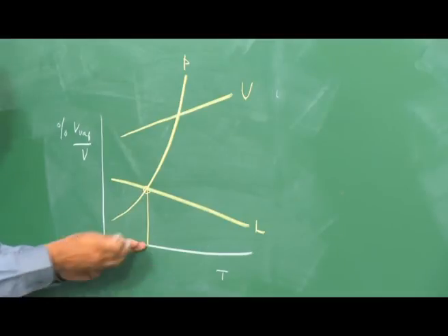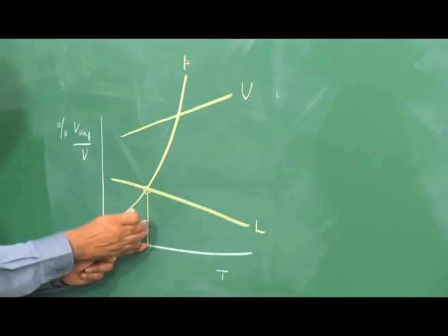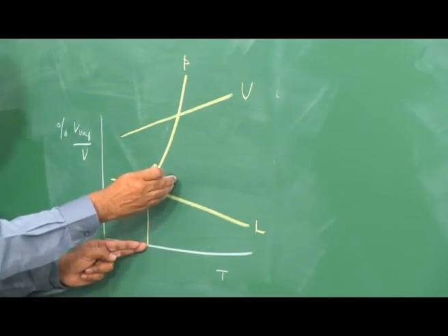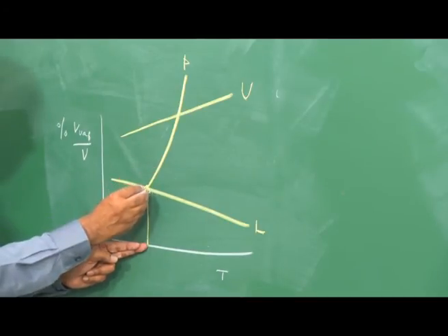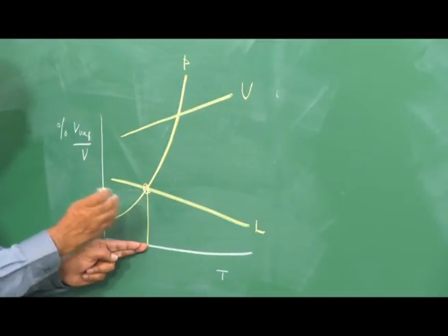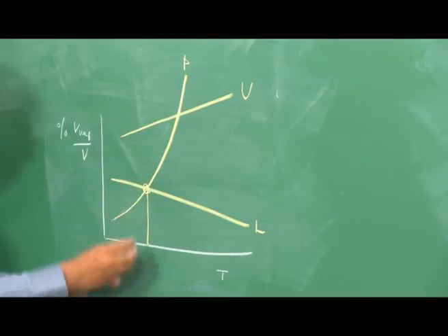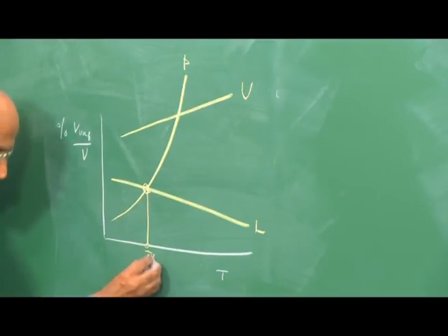I generate sufficient vapor which is just at the lean limit of flammability, and if I increase the temperature just above it, I have sufficient vapor which forms a mixture above the limit of flammability. Therefore, this corresponds to the minimum temperature of the volatile liquid at which a flammable mixture can be formed, and this temperature is what we call the flash point temperature.